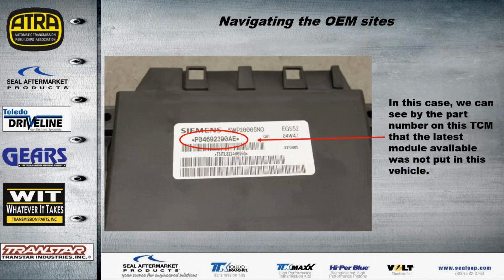Now, once we've established that there is programming available, the next thing we're going to want to do is look at the module and make sure, especially if it looks like somebody's been messing with the module, if they put their mitts on it or there's yellow paint on it like it came from a junkyard, we can match those numbers up versus the list that we have from that PDF file, to see if it is a valid module that can be programmed and work with this application.